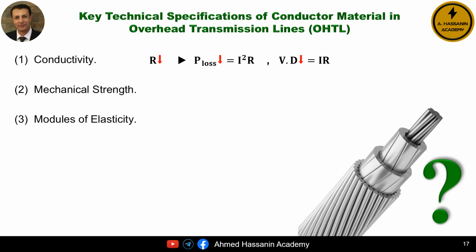The modulus of elasticity of the conductor should be low so that the conductor does not elongate excessively under the tensile stress caused by its own weight. Excessive elongation of the conductor leads to a weakening of the conductor and may eventually cause it to break.